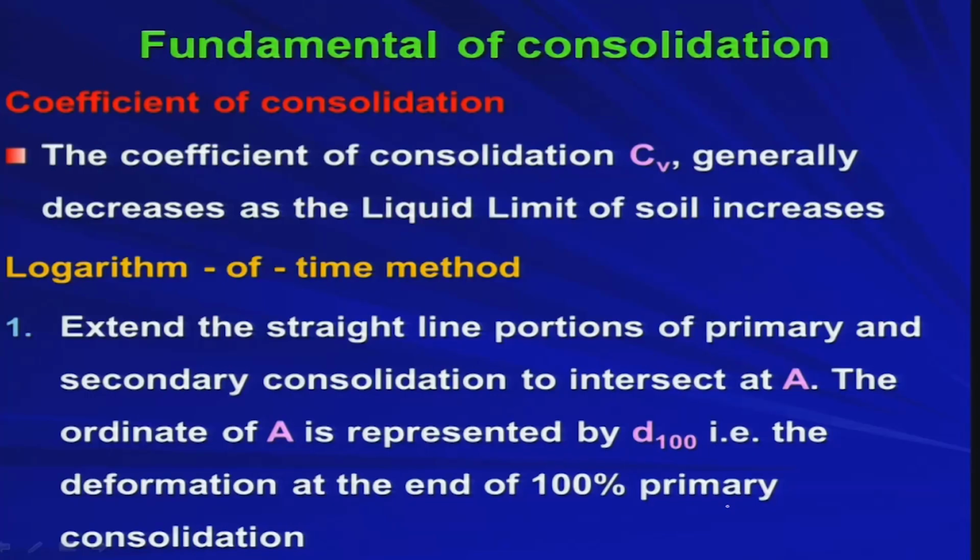Now, the coefficient of consolidation C_v, because that is another important term. I need to find out the coefficient of consolidation, right. If I know the coefficient of consolidation, then other parameters I can find out. So, how to obtain the coefficient of consolidation from your consolidation curve, or the e-log sigma prime curve?